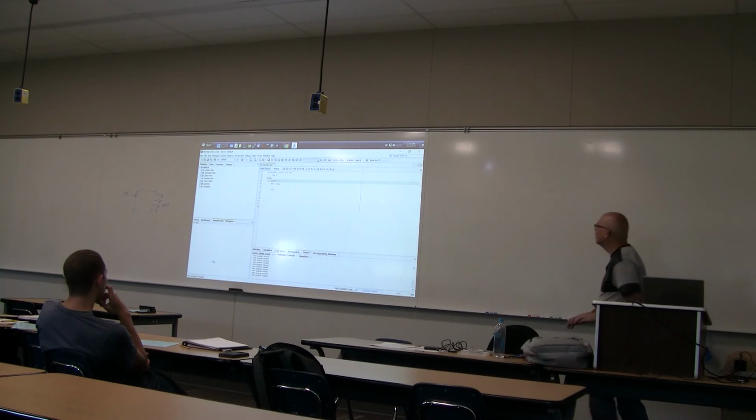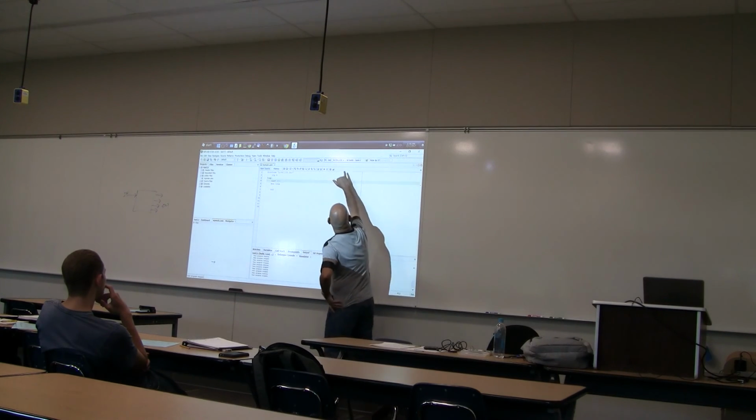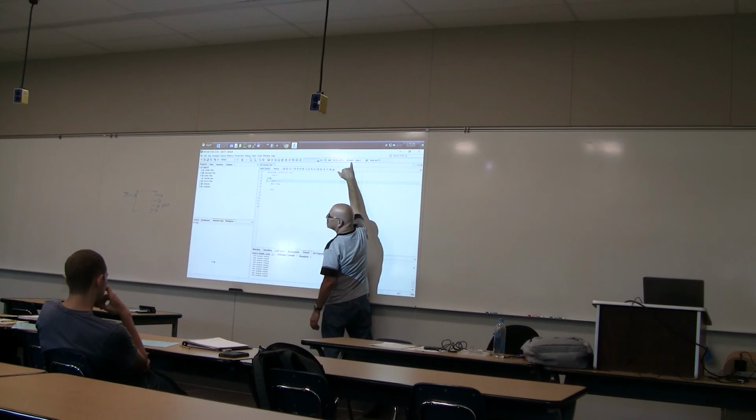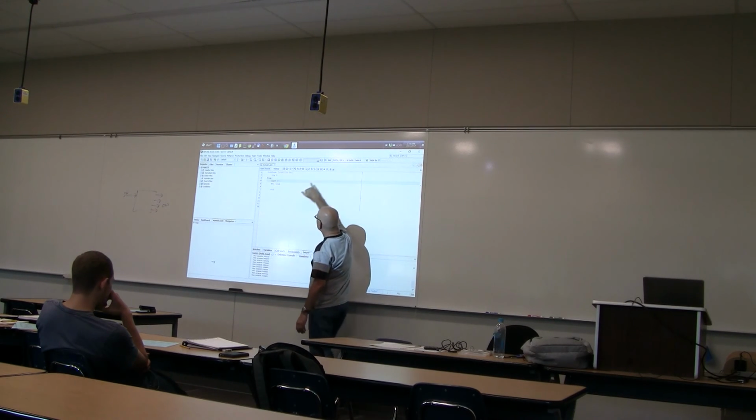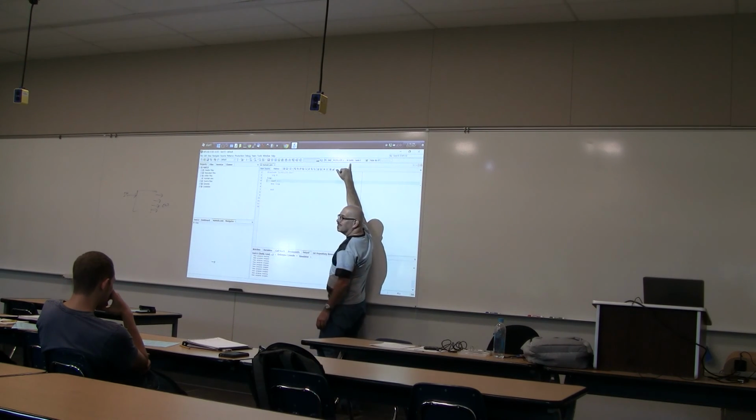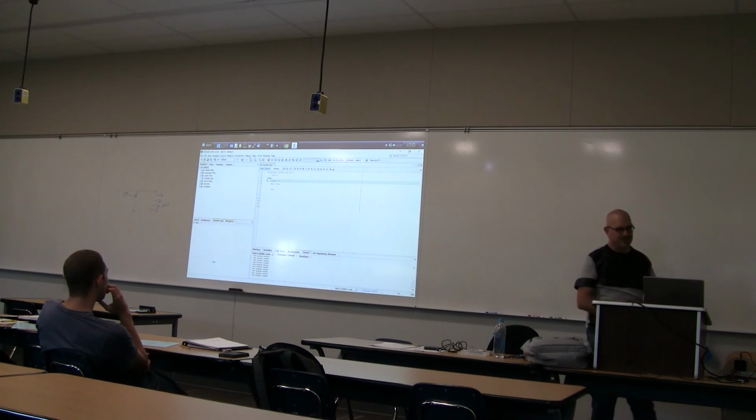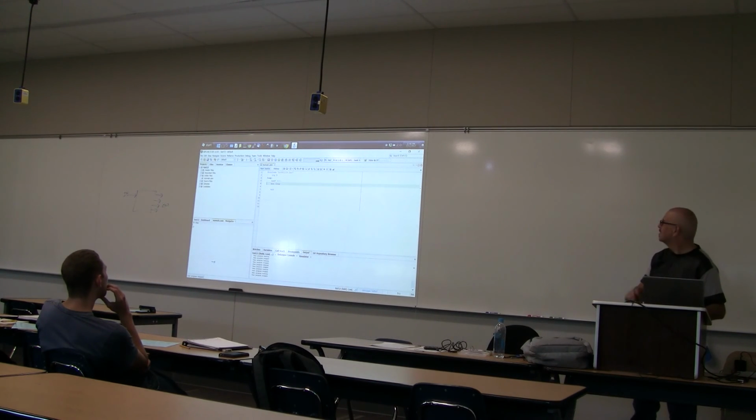All right, this is a little hard to see, but up here, there's some information, including the letter W, colon 0x80. That's the value of this thing called W-reg. And each time that I execute this instruction, this value should go up by 1. So if I hit an F7, W-reg changes to 81, and then 82, and so on. Right, so that's a really simple example of using the simulator to step through a program, one instruction at a time.